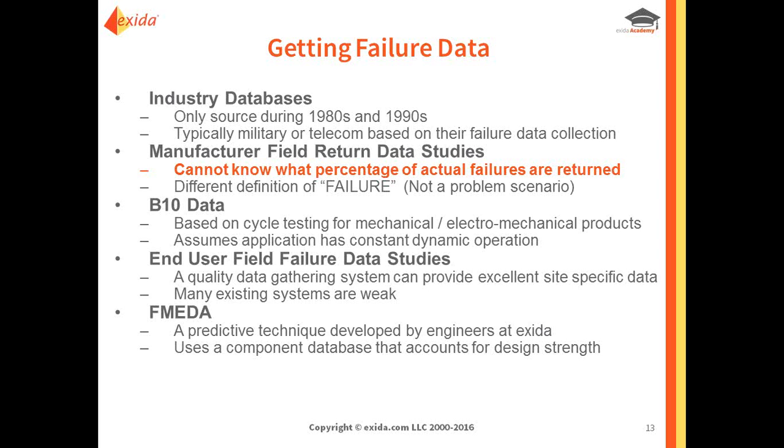You have to understand that when we're seeing this information, it's not just collecting it. You also have to realize what assumptions are being made, especially with manufacturers. You first have to understand, what is the scope? Is this a pressure transmitter with an impulse line, or without an impulse line? What kind of technology does this product use? Does it say that in the failure return information? What is the product number?